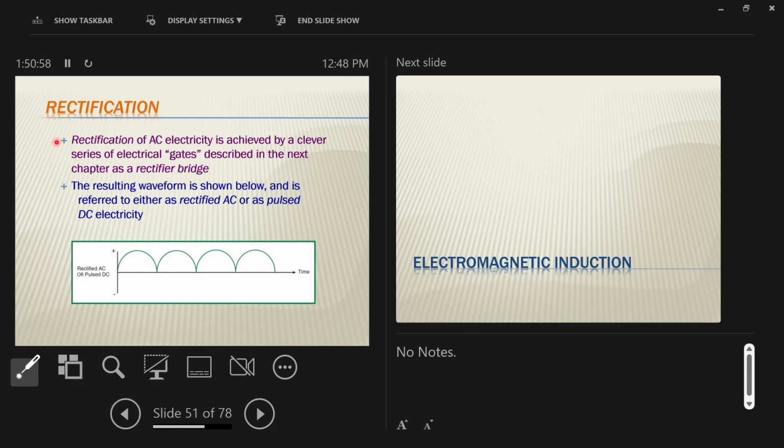So the advantage is it's easy to do. It takes one single device called a diode, and you only need one of them. The disadvantage is, with AC, you were making power the whole time, right? Now, you have a positive pulse here, a gap here, and another positive pulse after the gap. So there's nothing in the gap, right? Nothing in the gap. How big is that gap in time?